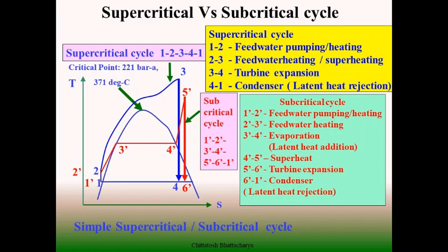At the same time, there are more statutory restrictions related to heat transfer rate, so that tube materials must be strong enough to withstand high temperature oxidation chances, and we have to see that the heat addition is taking place in a phased manner, so that transition from water to steam is smooth.